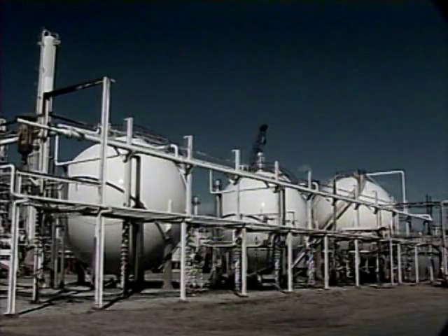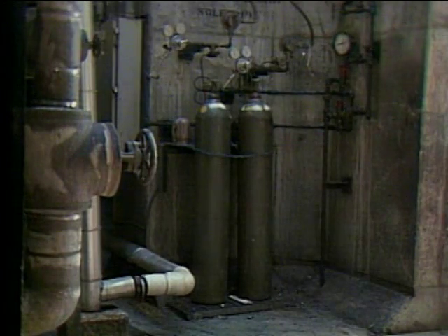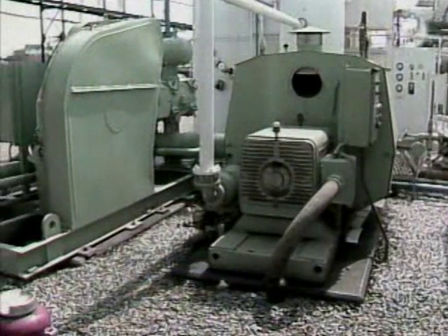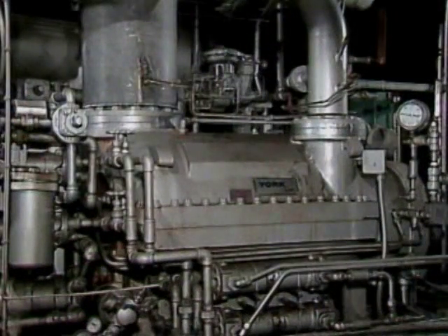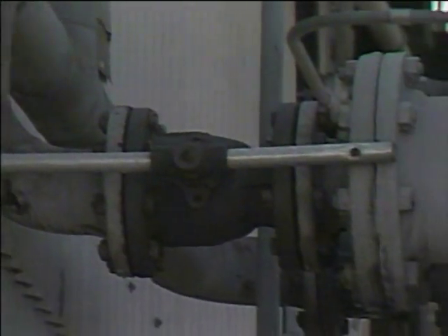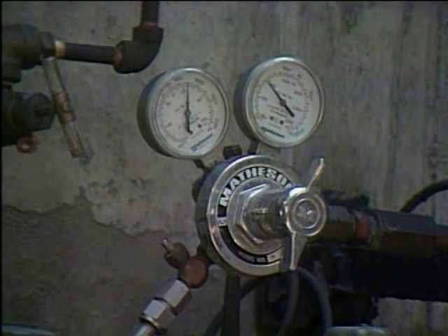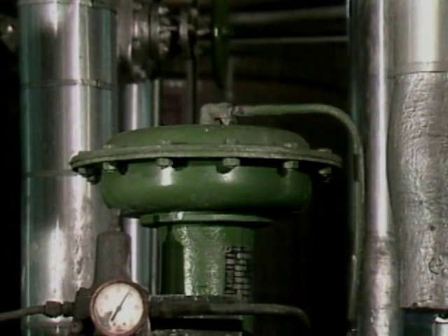Different types of gas and vapor systems can be found in process facilities. Although these systems may look different and serve different purposes, they each have to have at least 4 basic parts to satisfy certain key requirements. For example, a gas or vapor system has to have an energy source to provide the energy necessary for the system to perform its task, a transmission path to transport the gas or vapor from one place to another, control devices to adjust or change operating conditions in the system, and components to carry out the specific task of the system, and in doing so, create a demand or load on the system.